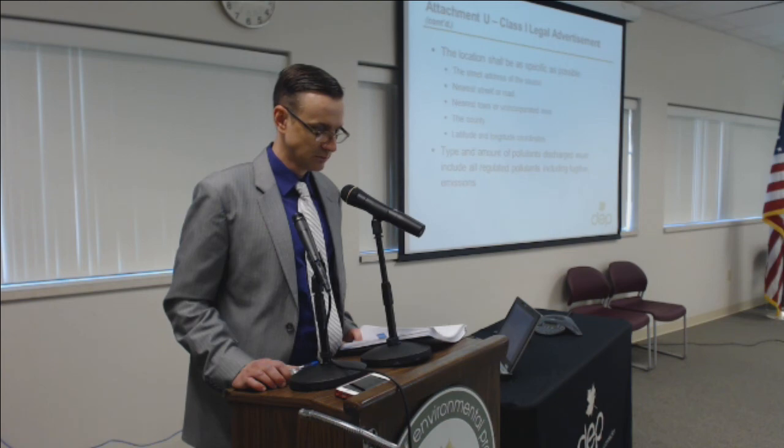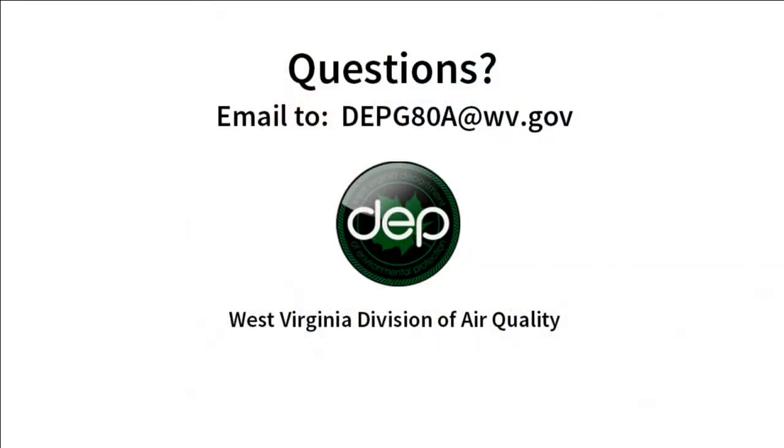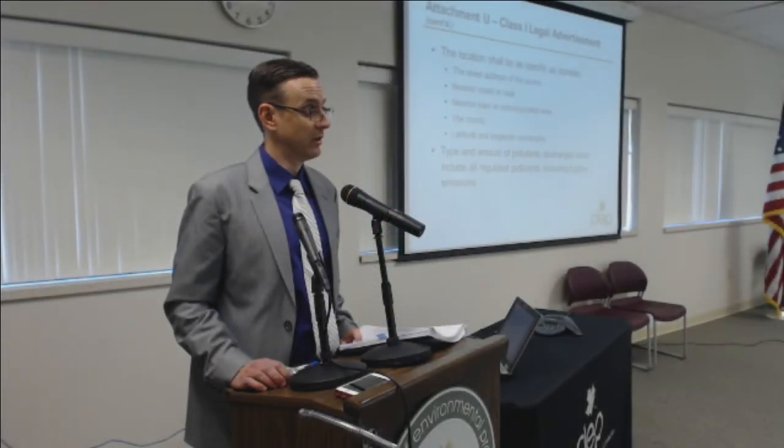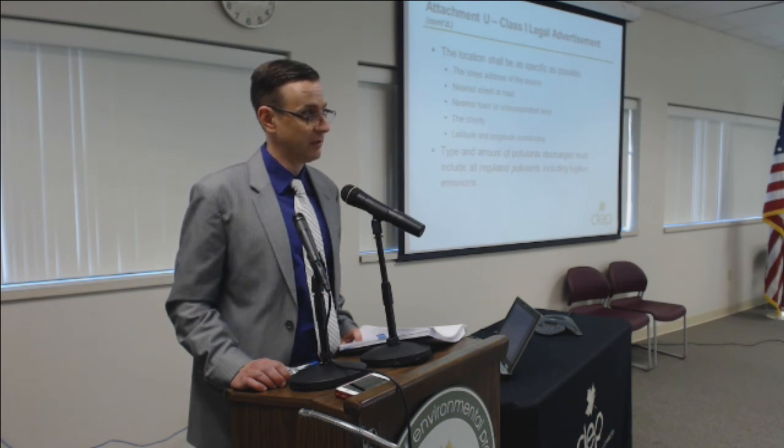If AP42 is an allowable calculation method for the tanker truck loading, and it does not have the ability to speciate, then you would need to include what it is that you have, because we will accept AP42 for the tank truck loading. So if it doesn't have the speciated HAPs, you would still need to include total HAPs for sure.